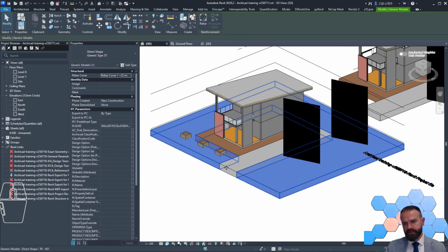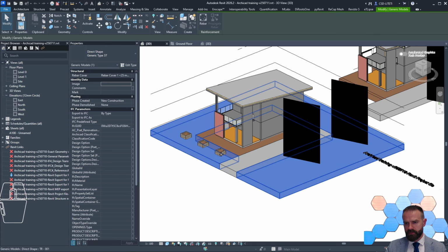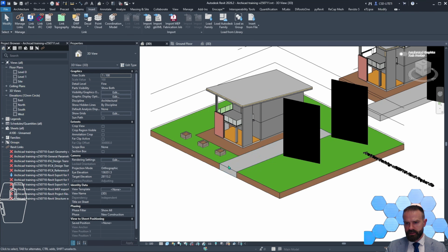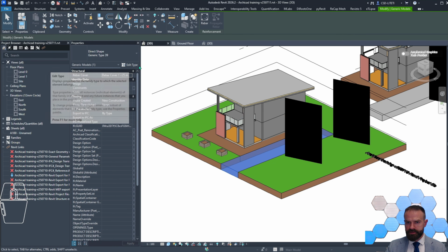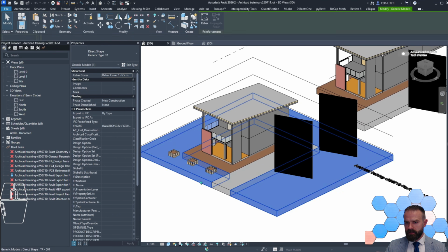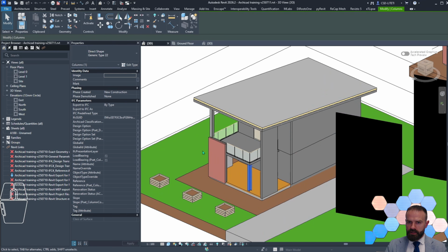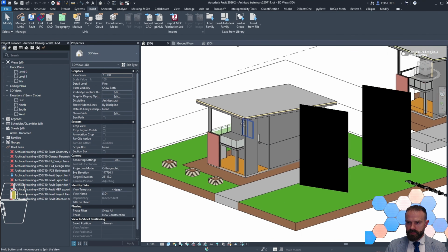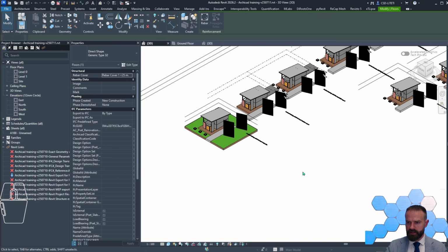So some components from direct export from ArchiCAD is better because I have side components like separate objects, it's direct shape, so I can just have different elements and I can select them. Other components was not converted, so I cannot modify because they are direct shape.